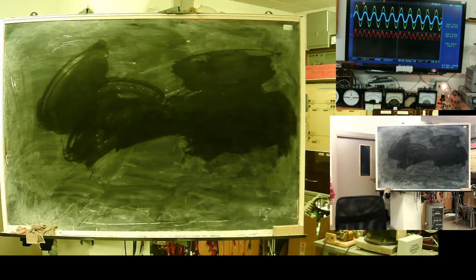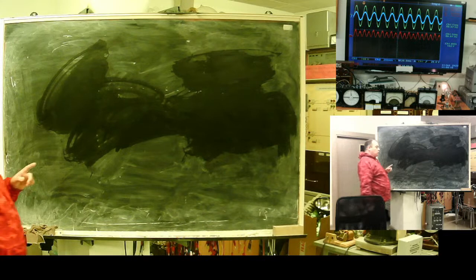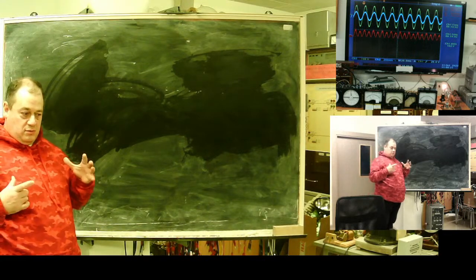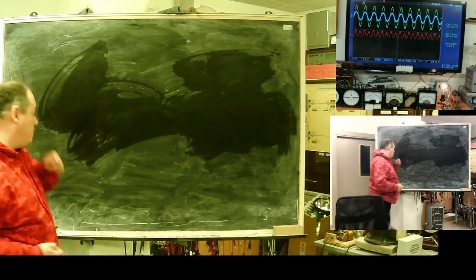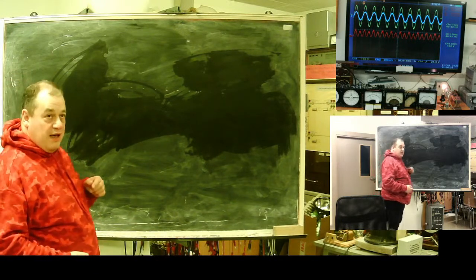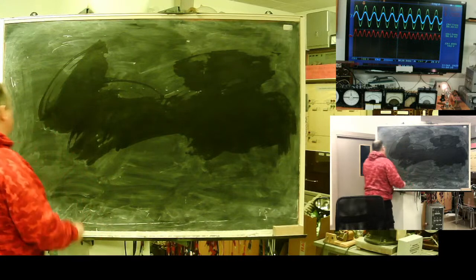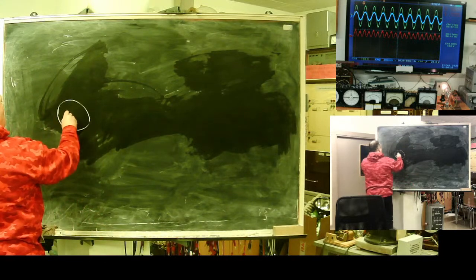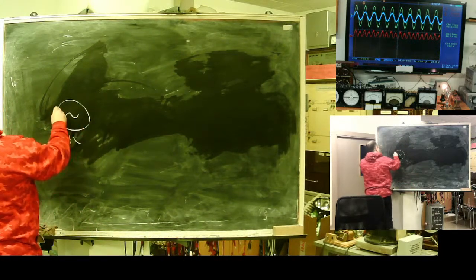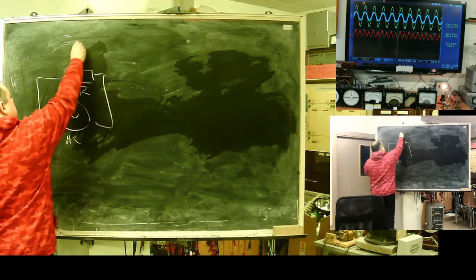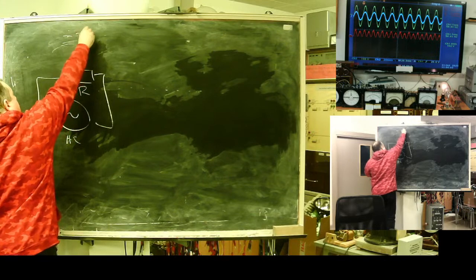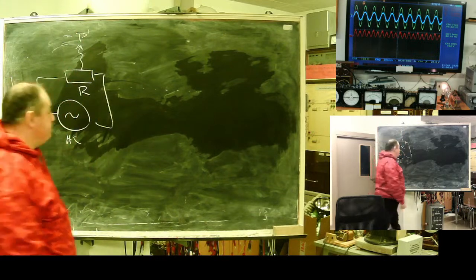To make all this calculus, or let's say mechanics, similar to a DC network, a special value, the effective value, was introduced. The idea: if we have our AC voltage loaded with a resistance, the resistance will heat with the power P1.